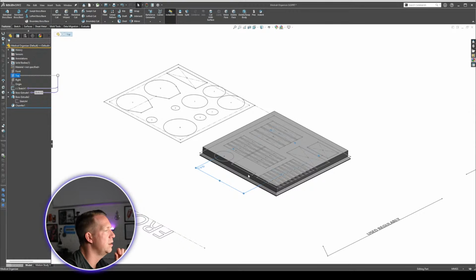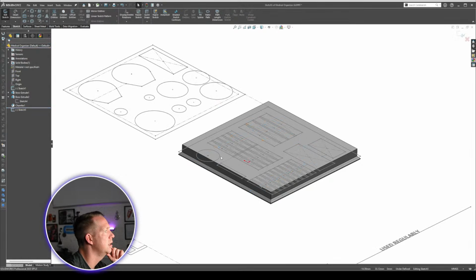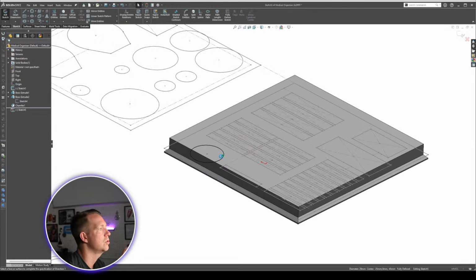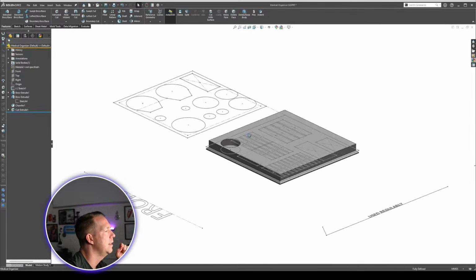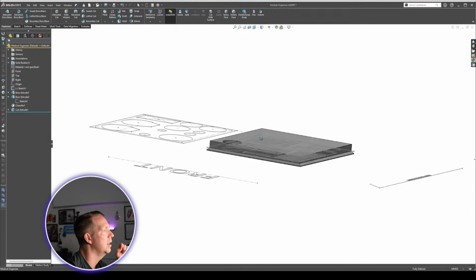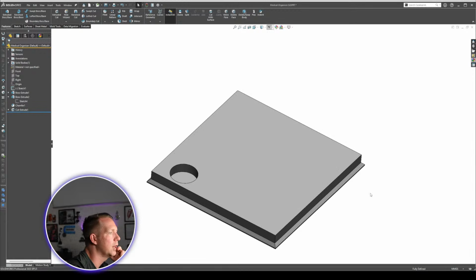All right, so if I want anything to come up from there, I can just start a sketch on the top plane, grab this circle, convert, do an extruded cut, just go through all, and that's starting to create my cutouts for my objects. So now it makes me think, how am I going to create all these cutouts? Do I want it to go into the material, or do I actually want to create all the dividers that are going around it? Or something in between that?